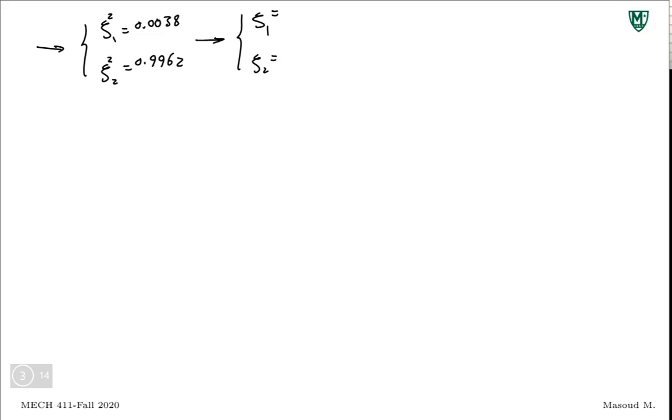So we said that we only have a maximum. In this case, that's the steady state value, the maximum. They said this is the maximum steady state amplitude in this problem statement. Now we said we only have a maximum in our curve when we are looking at the amplitude. A maximum occurs only if zeta is greater than 0 and smaller than 1 over the square root of 2.